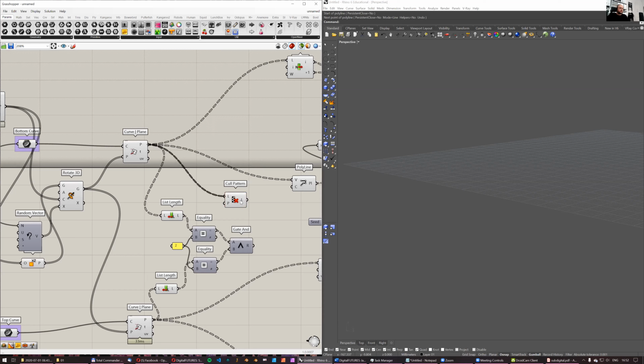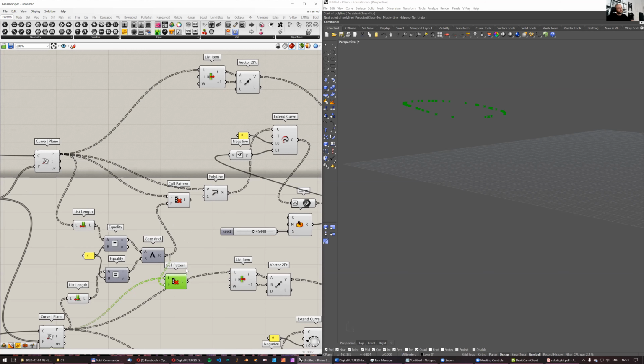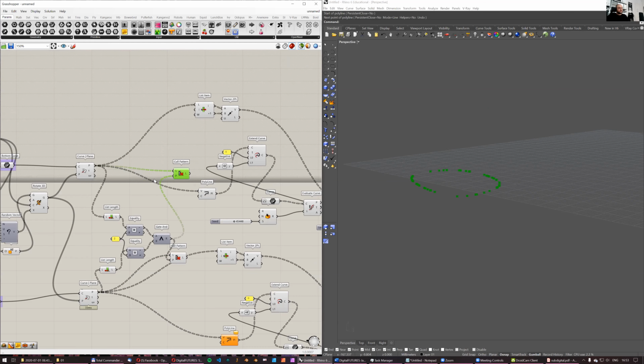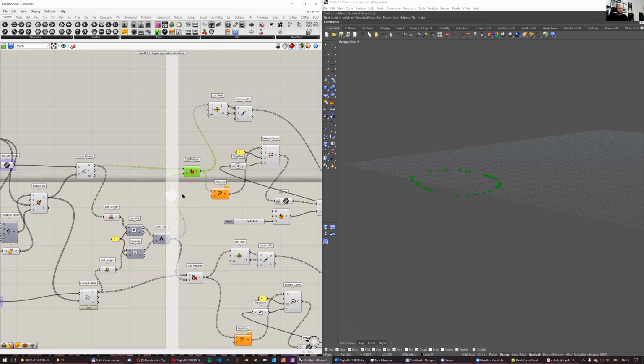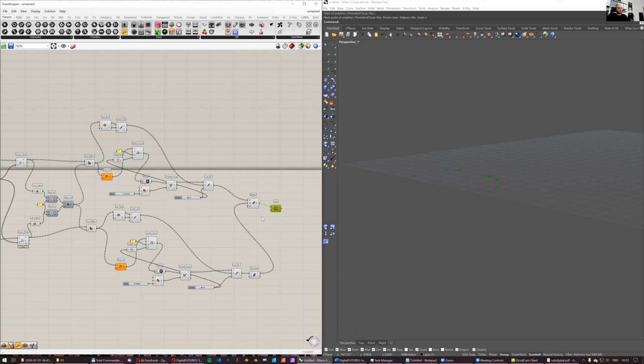Cull pattern, list pattern. Okay. If this works, then it's kind of easy, but I'm afraid it wouldn't. So this contains now 54 units. 54, yeah, this could work. So now this only contains those branches that contain 2 points. The other ones are just empty, and I will just reuse those. So I got rid of those possible sections that didn't contain 2 points on top and 2 points on bottom.